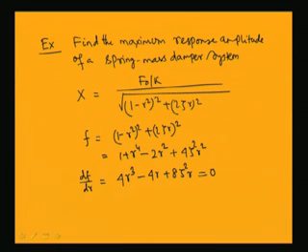So, I can take 4 r common here. So, 4 r into (r square minus 1 plus 2 zeta square) equal to 0. I can see that at r equal to 0 or at r square equal to 1 minus 2 zeta square, the response amplitude will be extremum.